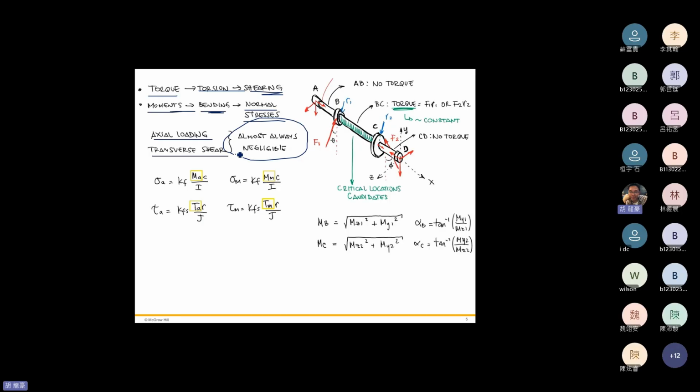Of course, the shaft keeps rotating. Therefore, it has to be treated as fatigue. As I taught for the fatigue criteria, the main two stresses we have to solve first to figure out the stresses for the fatigue failure are sigma A and sigma M.